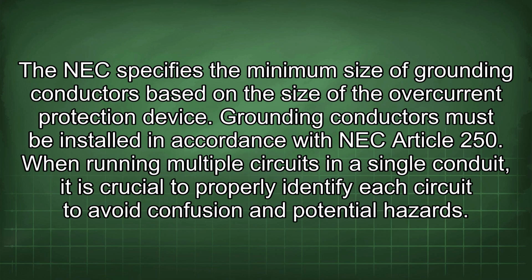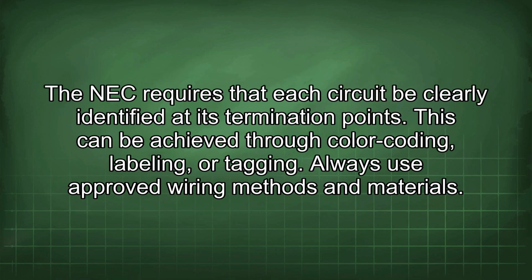When running multiple circuits in a single conduit, it is crucial to properly identify each circuit to avoid confusion and potential hazards. The NEC requires that each circuit be clearly identified at its termination points.